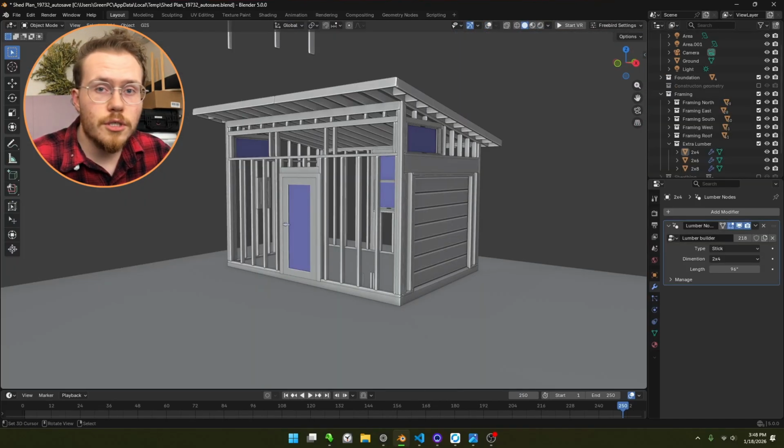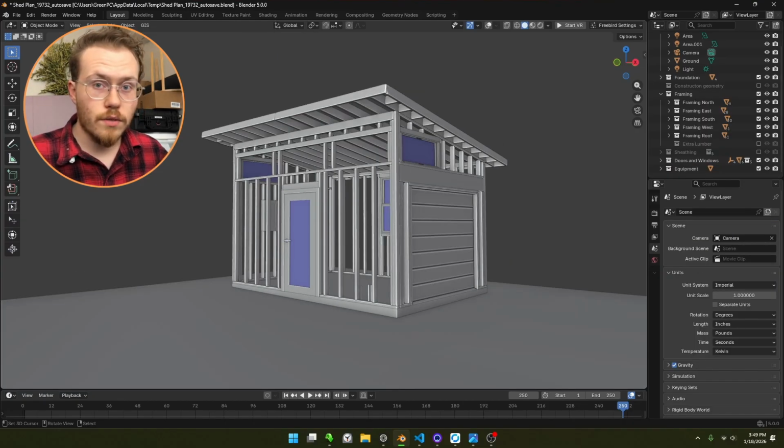Once the structure is put together and it looks good, now I just have to go through and count up the sticks of lumber, note what sizes, the thickness and width of them, as well as the length, and then convert that to nominal sizes that I can purchase. Then I can have a pretty good confidence that this will be ready to order, and I'll have what I need, and I'll have double checked everything before starting to build.